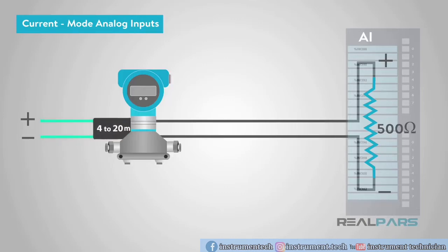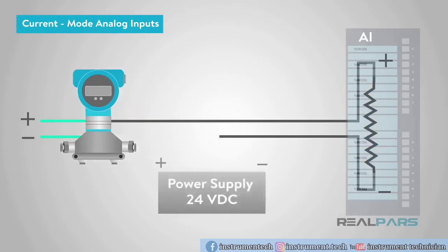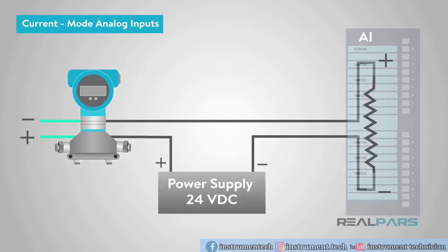Another common type of analog device uses the 4 to 20 milliamp signal as its power source, reducing the required complexity on the field end. Here's an example of a loop-powered arrangement. The main addition to the circuit is the separate power supply on the PLC end. Note that the positive and negative measuring device connections are different from the previous example. The current comes from the power supply in the positive terminal of the loop-powered device, and out the negative terminal and into the positive PLC terminal.